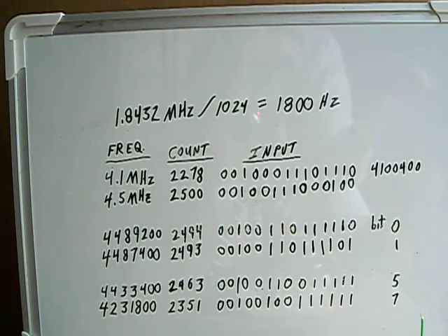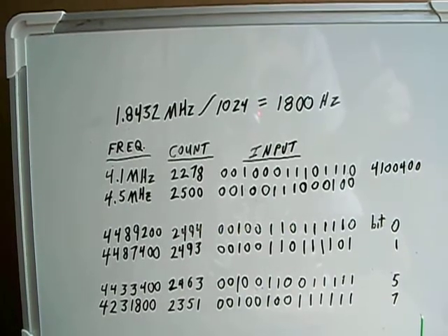I think that's because the Hartley oscillator isn't very clean. I could put a low-pass filter to tighten up that frequency, but the Hartley oscillator doesn't have much of an output. It's kind of marginal for the chip. The chip requires a minimum of 500 millivolts peak to peak, and the Hartley oscillator's output's about 700 millivolts peak to peak, so there's not a lot of room to add a low-pass filter there. The crystal oscillator output is 1.3 volts peak to peak. There's plenty of overhead for that, plenty of tolerance for that.